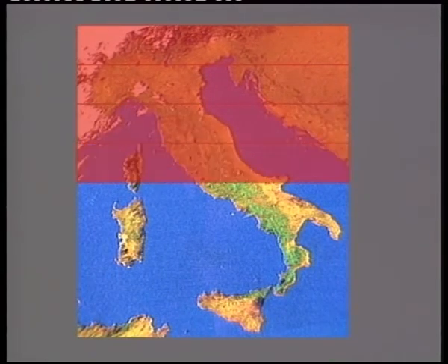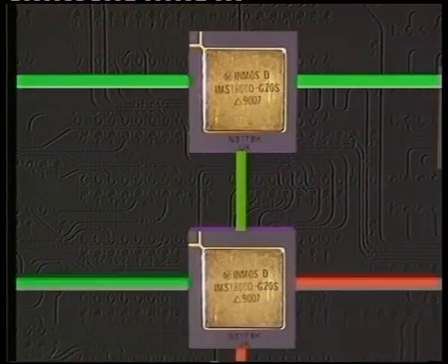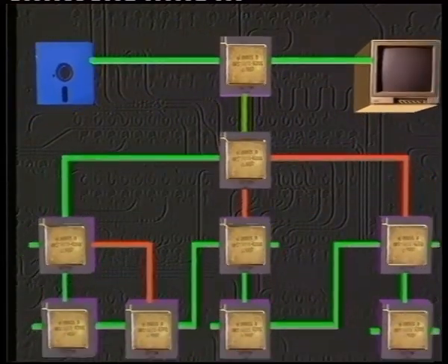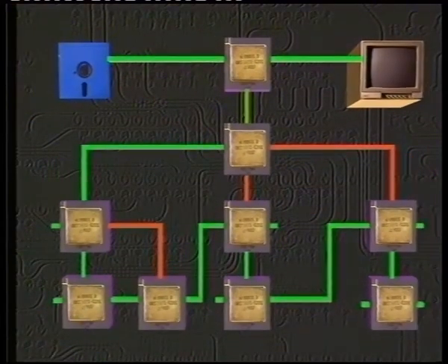In theory, speed is increased 8-fold, the number of transputers in the network, but in practice the figure is lower due to the time spent communicating between transputers. The strategy also exploits the maximum computational power of the transputer by reducing the number of communications between transputers and transferring large blocks of data for processing. The choice of the correct transputer network topology is crucial and must be based on the specific algorithm to implement.